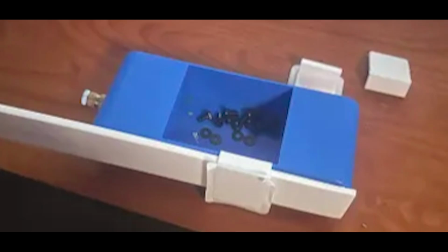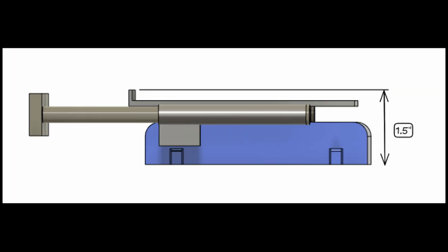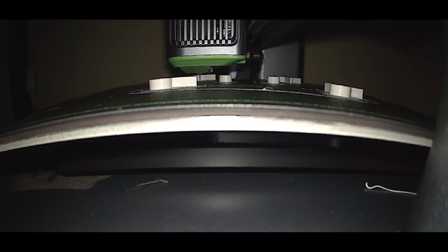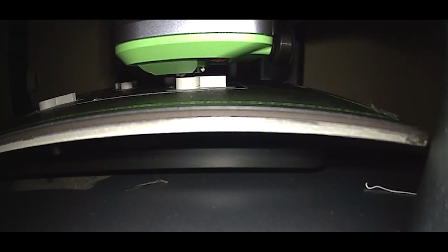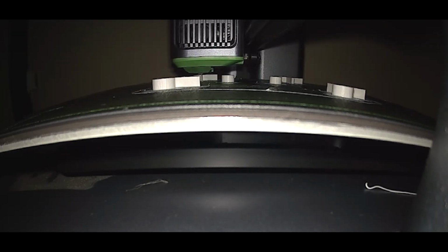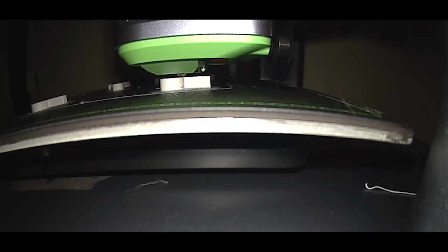By creating detailed assemblies, we could identify possible interference points, alignment problems, and weak structure areas before fabrication. Precise dimensions and tolerances were especially important for the sliding rod system and phone mounting assembly, because even a small alignment issue would affect repeatability during test. Once finalized, the CAD models were then used to manufacture several 3D printed components integrated into the final prototype. This significantly improved precision, consistency, and overall structure quality compared to earlier iterations.